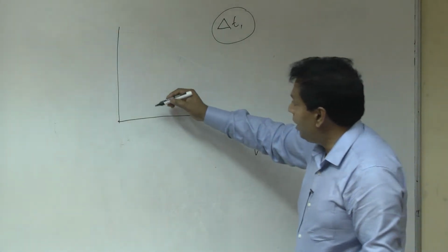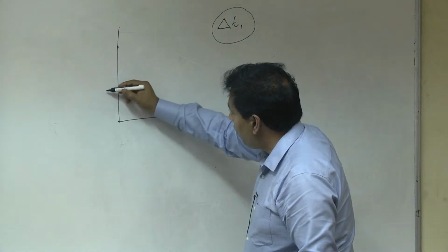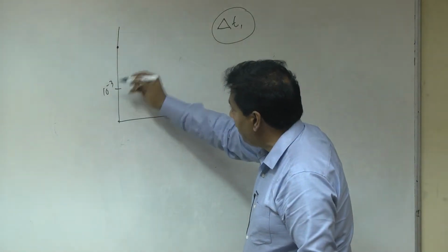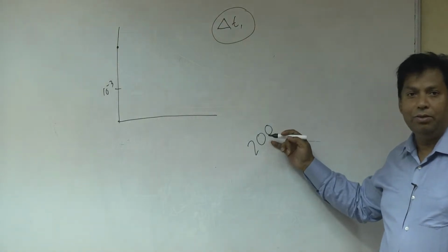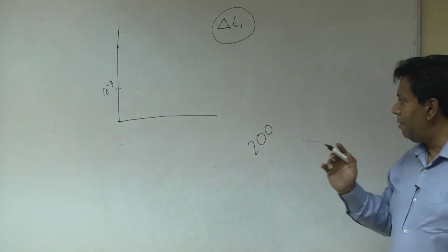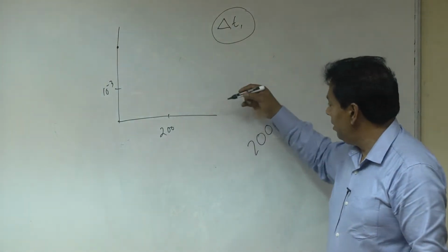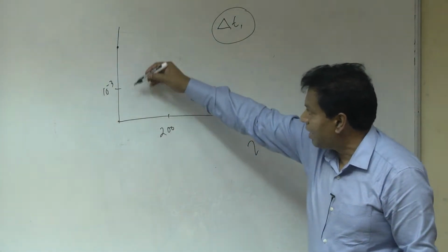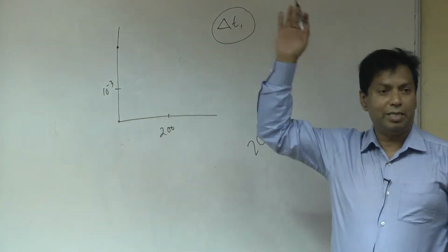And your solution is coming down from somewhere to your required residual of 10 to the power minus 3, maybe within this value. If it is not within this value, that means your solution does not converge. But sometimes, within this 200, it is coming here and not coming down to 10 to the power minus 3, so you are actually forcing it to converge.